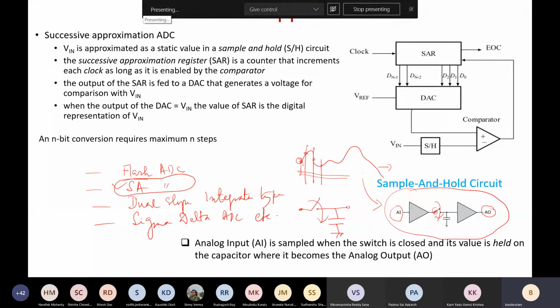Then we will not get all the continuous data over here; rather we will get some discrete data at this point, fine. And then the capacitor will store that charge. So if you look at the capacitor output, suppose we draw it bigger: you are switching in this interval like this, so this data will be stored at the capacitor, and until it gets the next sample data, it will hold that value.